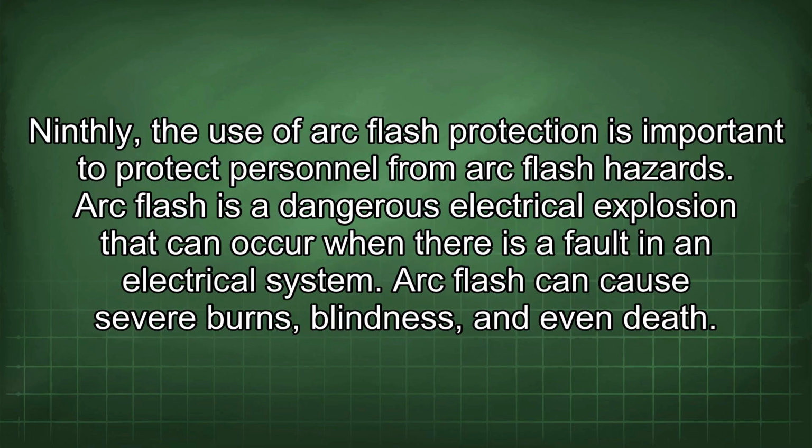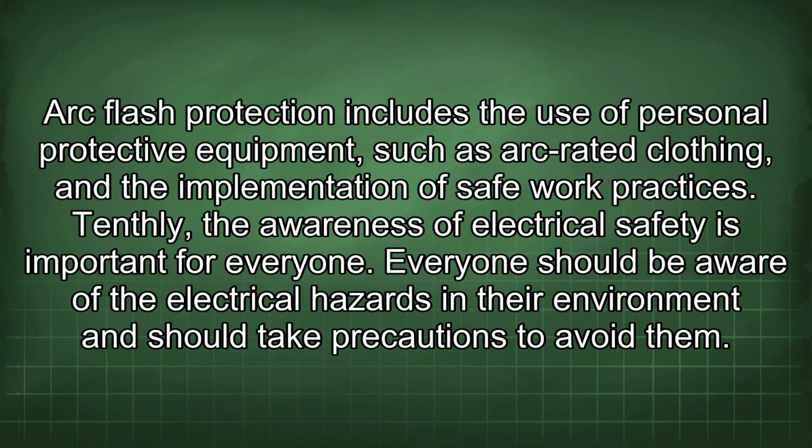Ninthly, the use of arc flash protection is important to protect personnel from arc flash hazards. Arc flash is a dangerous electrical explosion that can occur when there is a fault in an electrical system. Arc flash can cause severe burns, blindness, and even death. Arc flash protection includes the use of personal protective equipment such as arc-rated clothing and the implementation of safe work practices. Tenthly, the awareness of electrical safety is important for everyone.